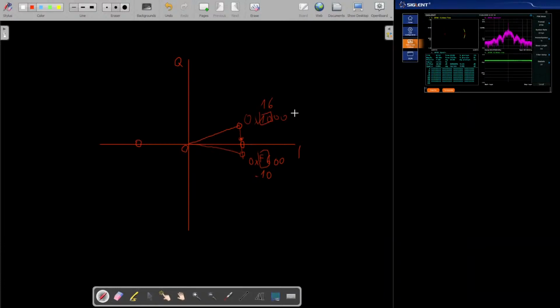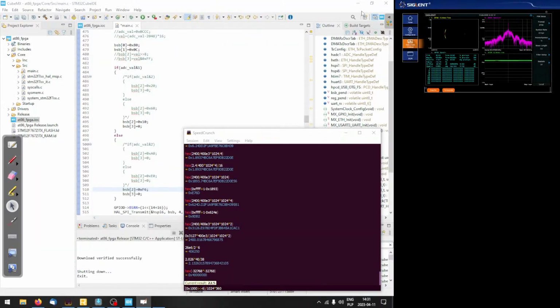So let's get back to this, and let's think about what the correct value should be. For the BPSK, we want the phase shift to be 0 or 180 degrees. But in our case, we can actually do something equivalent to that. We can either set the carrier to plus or minus 90 degrees, which is going to cause exactly the same effect. So let's do some arithmetic again.